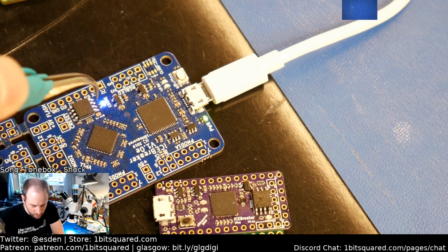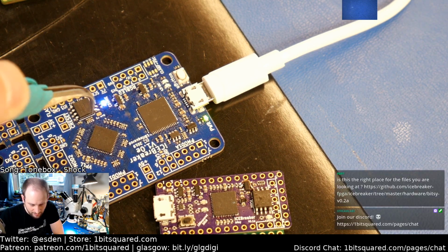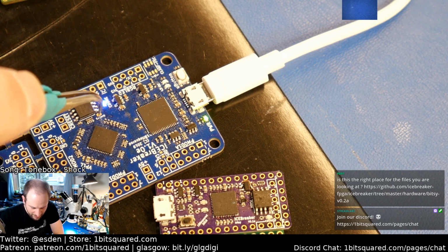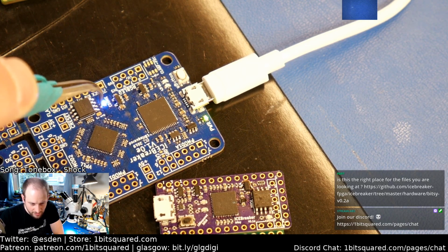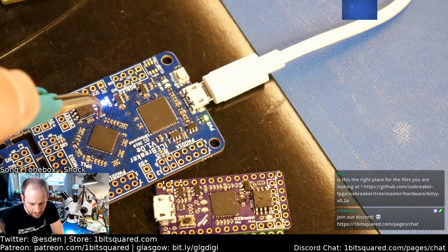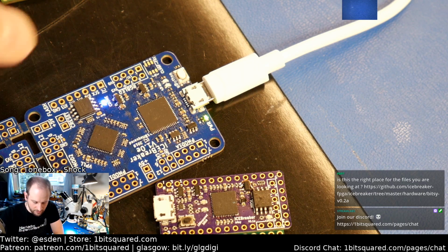So what you can do is solder piggyback an SRAM chip onto the flash chip and use this pad on the side here. This is what this pad is for, and bend the leg a little bit to the side and solder the chip select of the RAM chip to the additional signal. So you can then select between the flash and the SRAM on the same board.